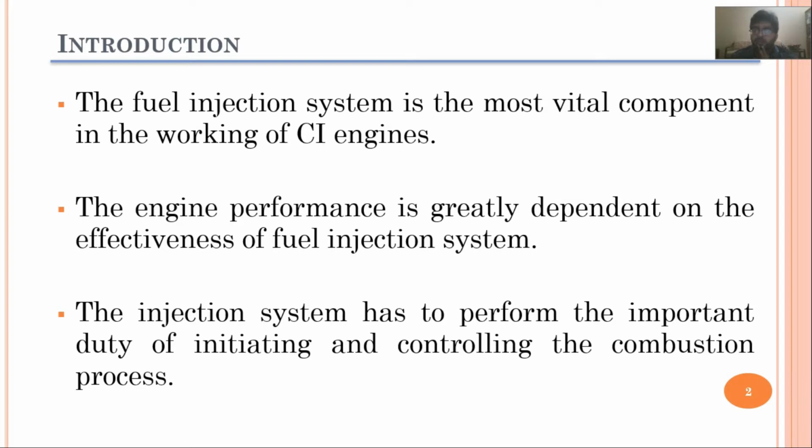The injection system has to perform the important duty of not only initiating but also controlling the combustion process, because the fuel is not injected instantaneously. It will start spraying the fuel, and it will continue spraying for quite some duration of time, depending upon the engine speed and load.